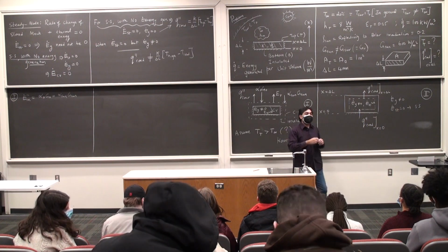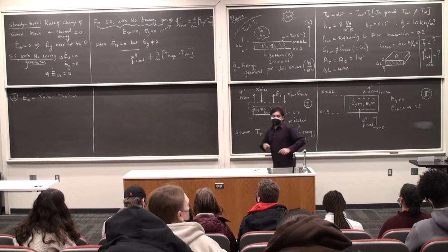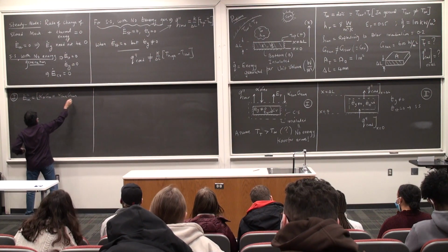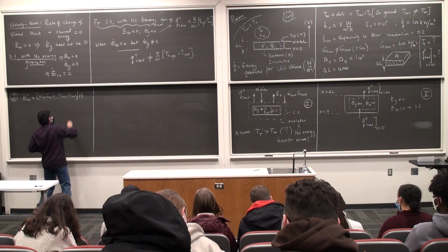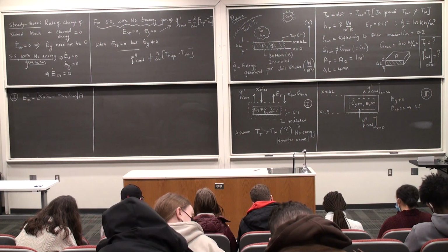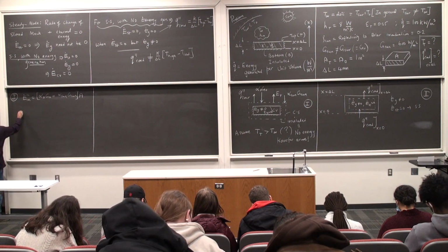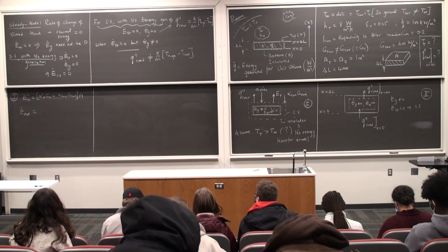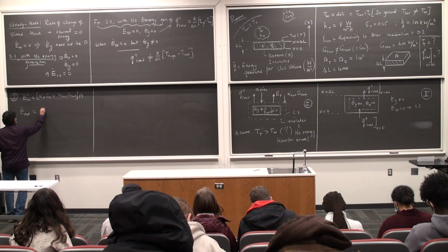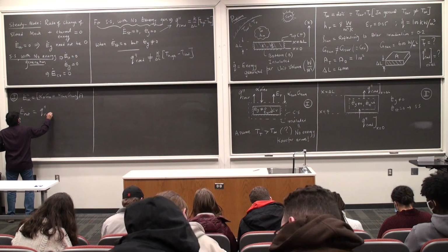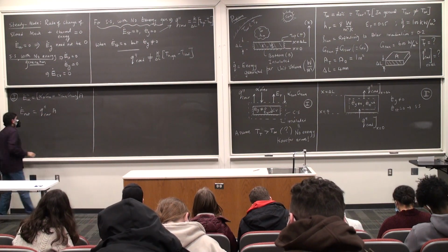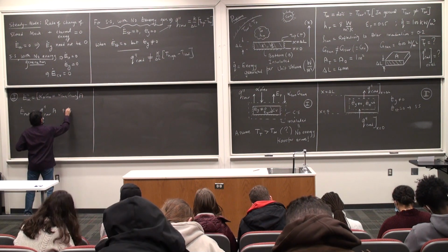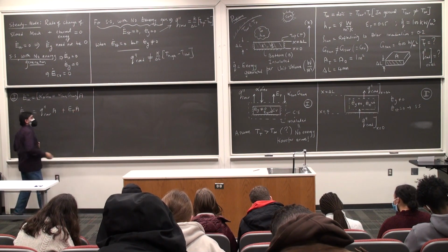Shouldn't you be multiplying those by areas? Absolutely. The areas are the same for both, top and the bottom. And this has to deal with the top surface. So this is multiplied by A. E dot out: the convective flux going out of the top surface multiplied by the area. Then I'm going to have E suffix T, which is the emitted flux multiplied by the area.